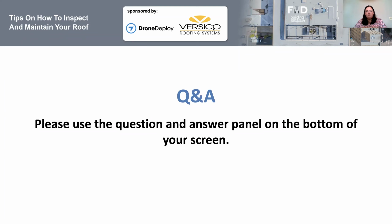Perfect. Andrew and Chris, you both kind of talked about, for thermal imaging, it's more important about time of day. Andrew, you mentioned you do yours half hour after sunset. Obviously, that's what you would recommend. Somebody's just asking the best time of day and time of year to do thermal imaging on their roof. Yeah, don't do it if there's snow on the roof. That's the first step. Beyond that, time of year is not a big thing.